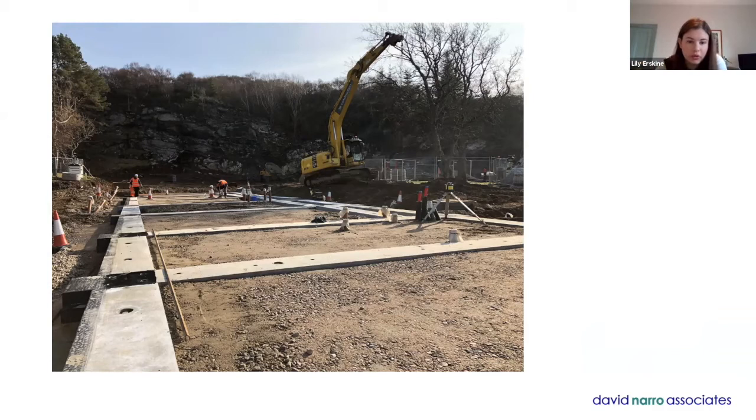You can see there that we also did infill just to add a little robustness, because when you cast something in a monolithic sense, it is solid. If you put in joints, you do get a little bit of movement, so you have to design that in. So things that we added in, like packing in ground in between, so that compacted soil is all from a small plant that we set up on site. When we reconfigured the landscape, we regraded into a type 6N mix and compacted it in between the precast elements just to enhance that robustness.